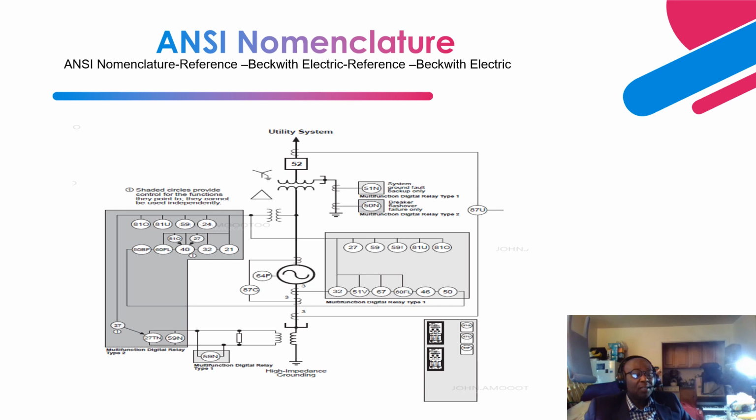Next is 27TN. This is a third harmonic undervoltage relay, and it complements 59N. Like I made mention, the 59N stator ground fault relay is made to see only 95% of the stator winding. So the remaining 5%, this relay does not see and does not cover that region.